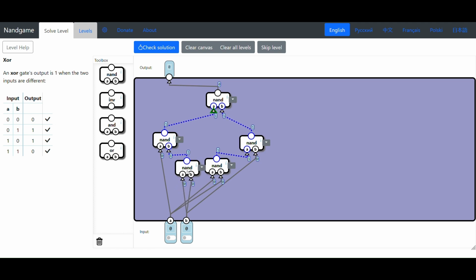If you can see what I see, these two NAND gates have a very similar purpose, and it's so similar that we can actually replace them with a single NAND gate for each input. That way. So these two are both 1, and if we turn one of them on, if we connect it like this, you can see it still has the same functionality to it.